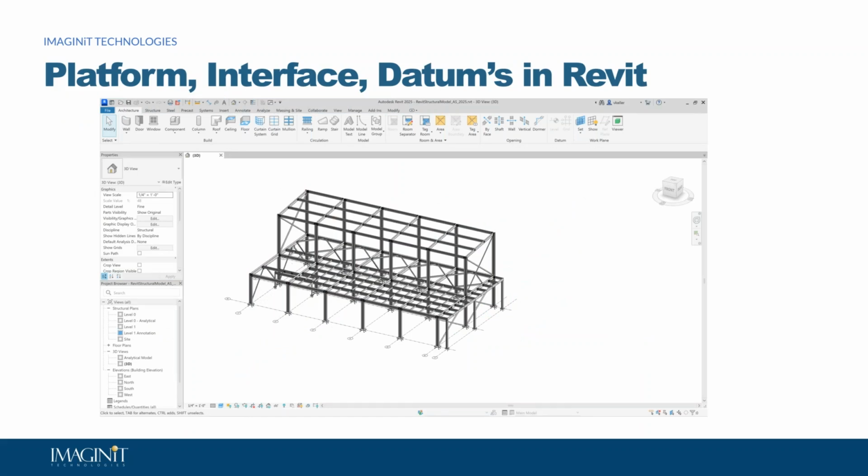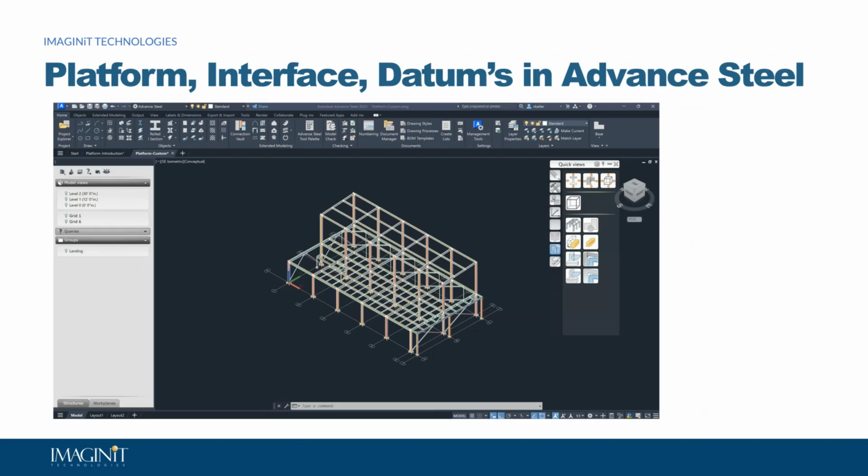How do I start a project? This is the look of Revit. We have a ribbon interface on the top, with tools and panel names for organizing the different commands. You'll see palettes like Properties and Project Browser, and ways to get around the model. If I were to begin something new, I would start with a correct template. Then I would start designing grids to place columns and other things so I can figure out where things are located. Then I would think about my floor-to-floor height, my levels. That's also true with Advanced Steel.